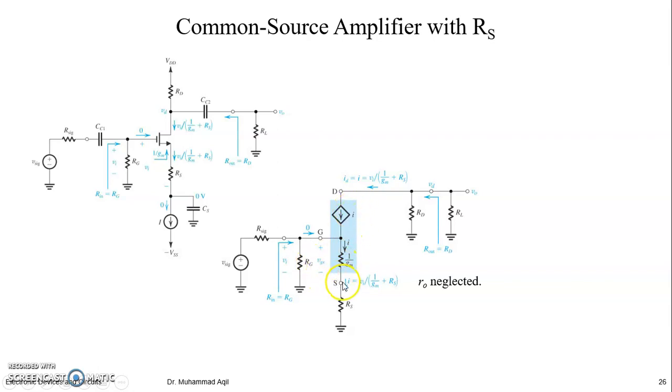Okay, so then attach the things as source. We have a source resistance, other things are bypassed, so it's not available in the AC circuit. If they're in T model, you were recommended previously that you don't need to take the R0, the early effect resistance, and then just put RD as ground and RL as ground, right? Because this will not be appearing in the